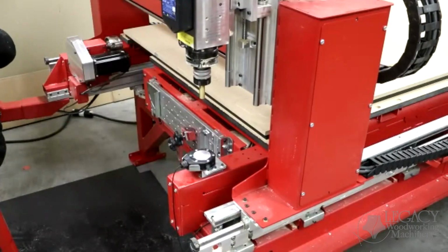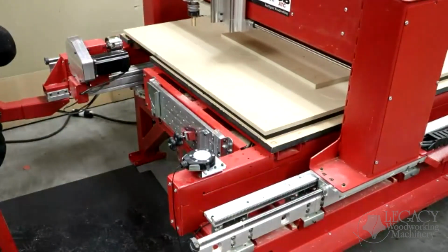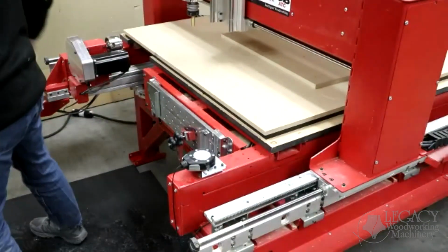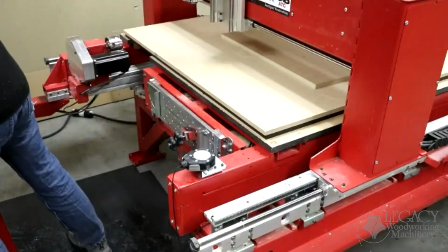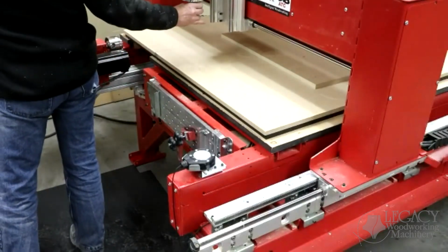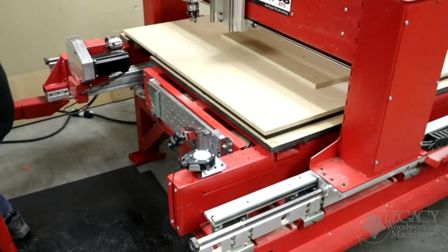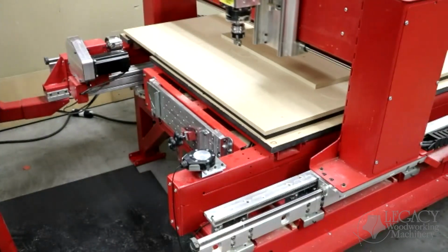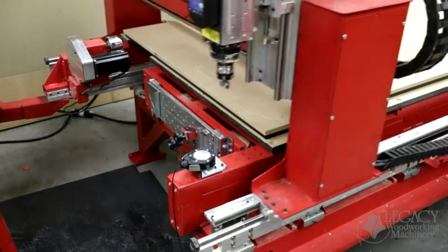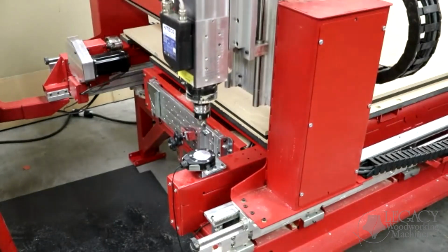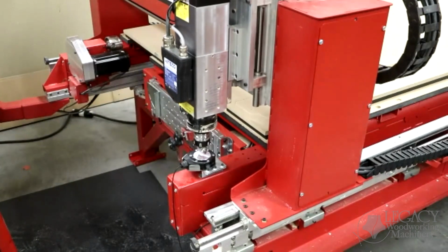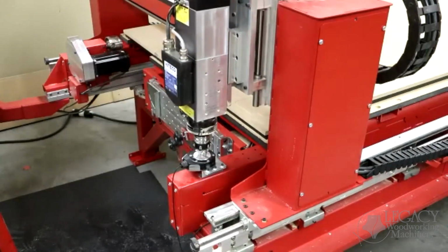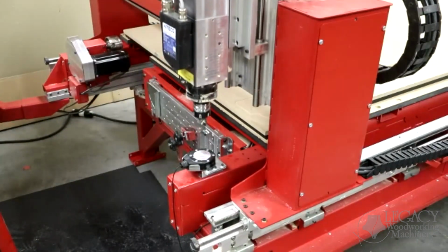Okay, so I'm executing the tool. So it's gone to the manual tool change position. Again, it could be the auto tool change, doesn't matter. Okay, this tool is a little bit shorter, but I'm going to go ahead and run this. It's going to go touch off the Smart Tool, and watch how far it rapid Z's. Okay, quite a bit closer because this tool is just a little bit shorter than my other setup tool. But that makes it very, very quick.